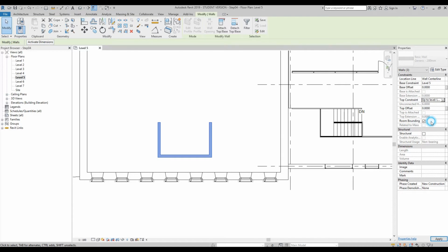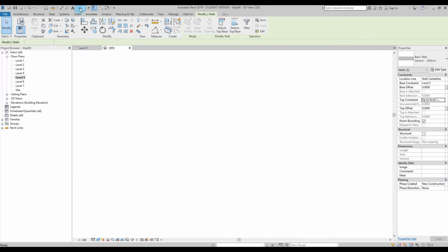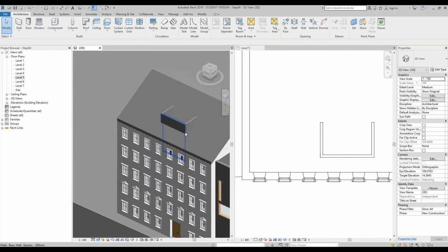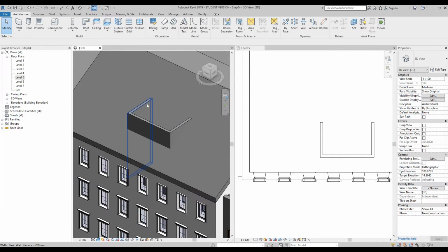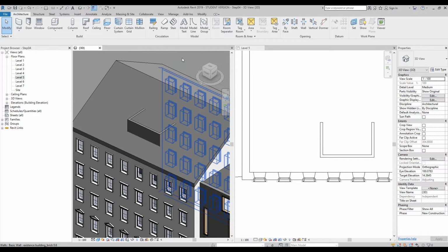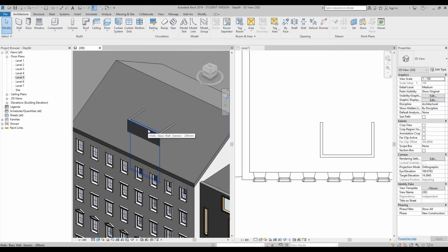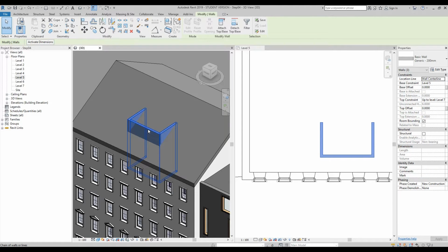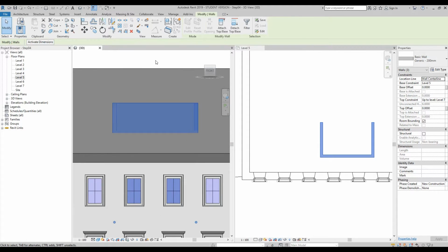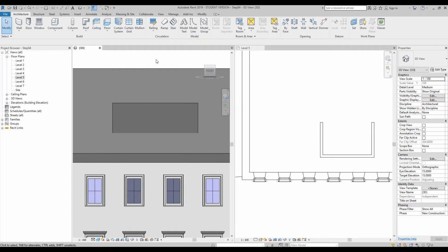up to level 7, and then if you go to your 3D view and your quick options bar at the top here and then press WT again and zoom in to those 3 walls, you will notice that they have popped out to the top of this roof. Okay, staying in our 3D view, if you hover over one of these walls, press tab once and click your mouse, and then in the view cube press the front, it will zoom into that area. Then I want you to press in negative space just above the roof.